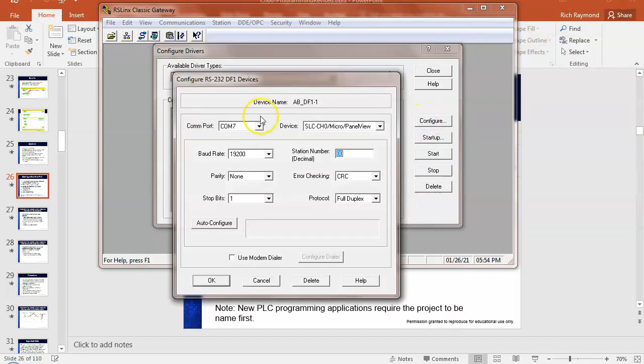So I can configure, and then you would have to select what COM port that it assigns it. Does that make sense? So you got this little scroll button right here, and you could go in and find that COM port that shows in Device Manager. So Device Manager shows that, and you can find that. And then that's all you have to do.